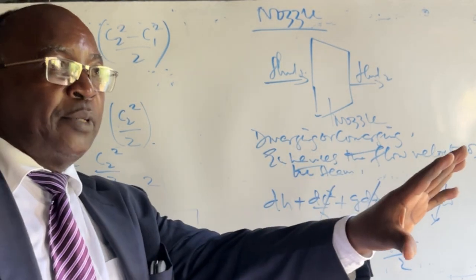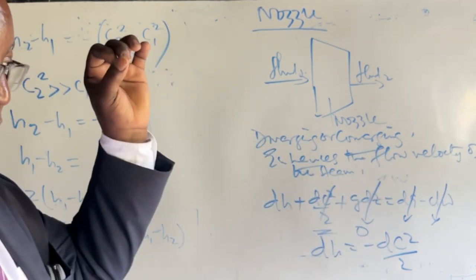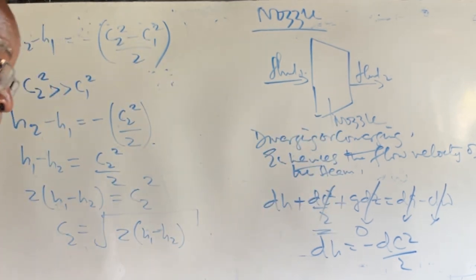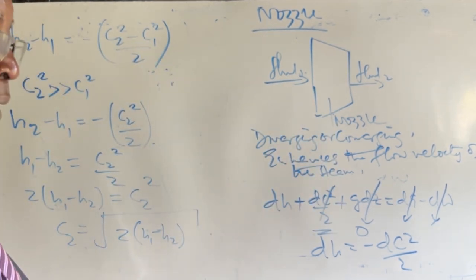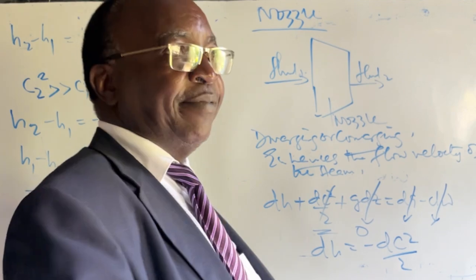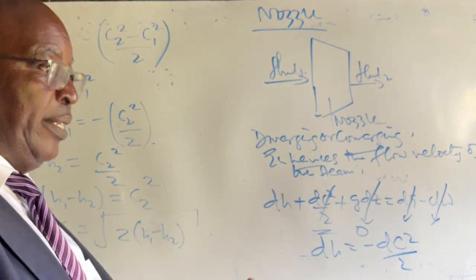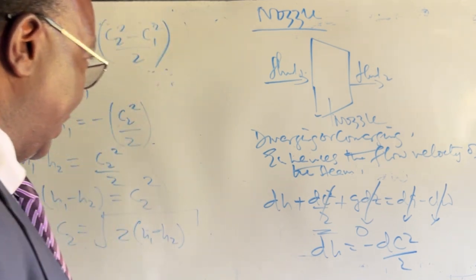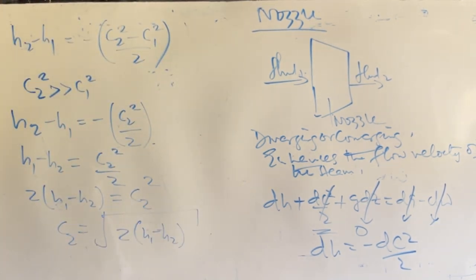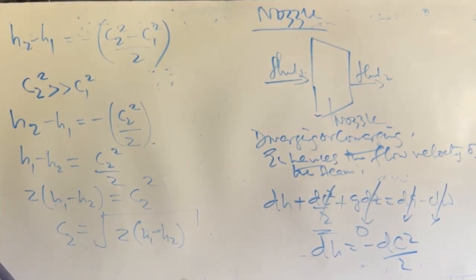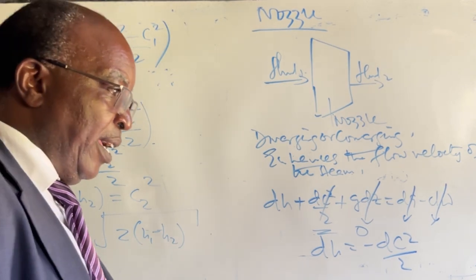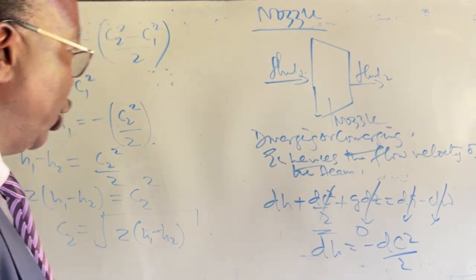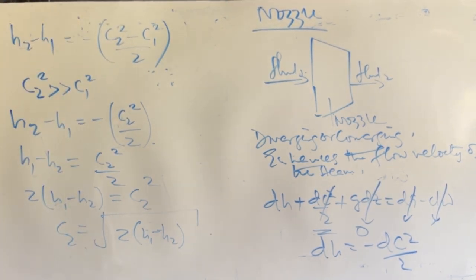You can form superheated steam or a wet vapor. Wet vapor means you're in the region where there's equilibrium between vapor and liquid. And of course, when you talk of those, there's also what's called the lever rule. It's able to tell you the moles of liquid and vapor when you look at temperature versus composition and so forth in phase equilibria. So all these things are married together.